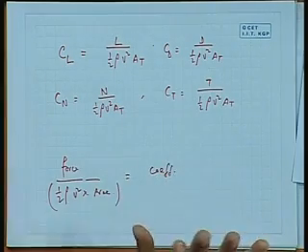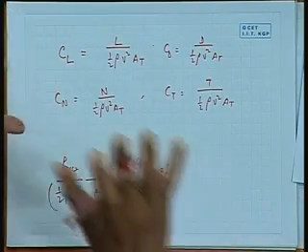And it's a fluid dynamics trick that whenever you cannot figure out a force, you simply call the force equal to some coefficient into half rho v square into an area. Just as you call Cf, half rho v square into surface area, and you call your total resistance coefficient, half rho v square area. So this is nothing but a way of non-dimensionalizing the force, and you call that unknown thing a coefficient, which I don't know, and I have to find out.